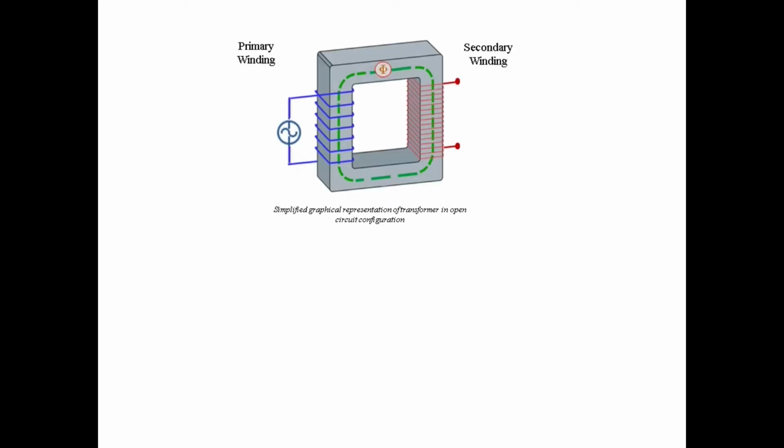For the open and short circuit tests, the voltage is normally connected to the primary and the secondary side respectively. This is basically due to limitations of some measurement devices. For open circuit tests, rated voltage is applied to the primary or the LV side of the transformer. In this example, the rated voltage is 230.